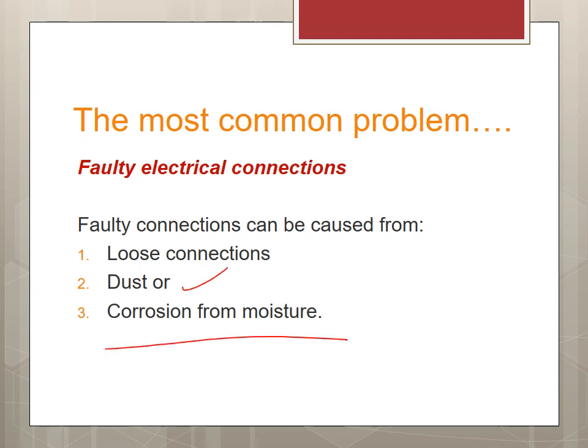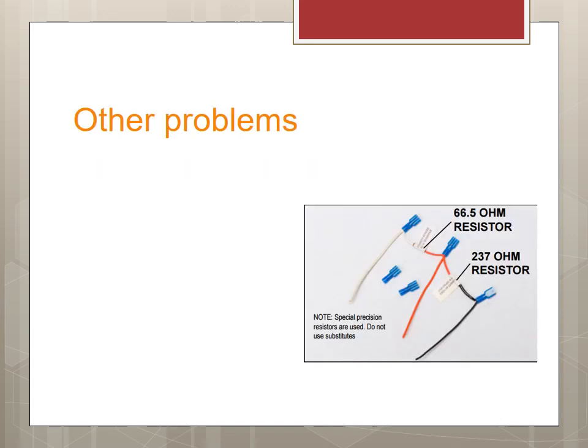There could be a leak in the plant or a steam leak somewhere, and that steam or rust or water can cause corrosion in some of the wires or connections. So again, we want to check the connections and the wires, even the sleeved ones, because sometimes they're really hard to get to, but you can have some corrosion inside those little connections.